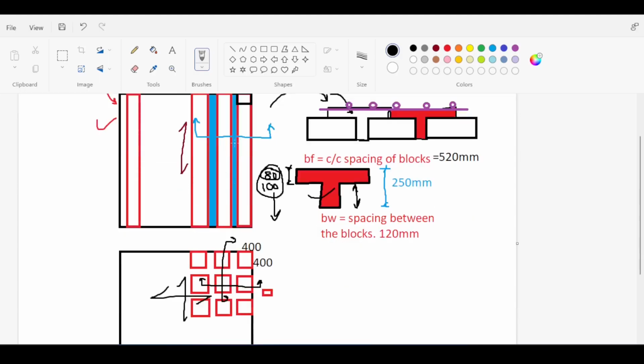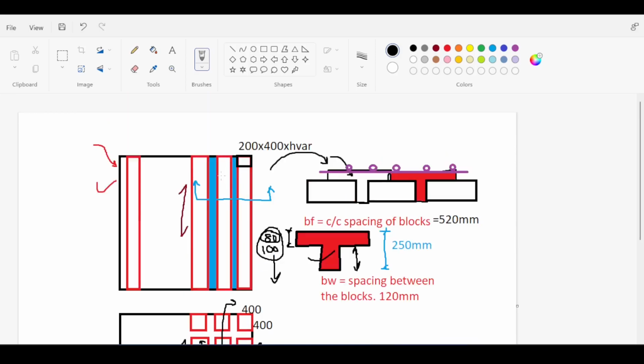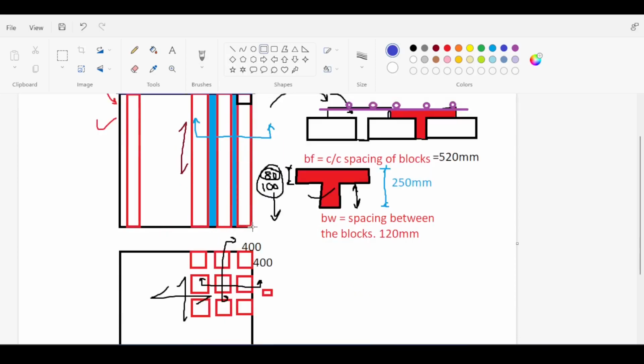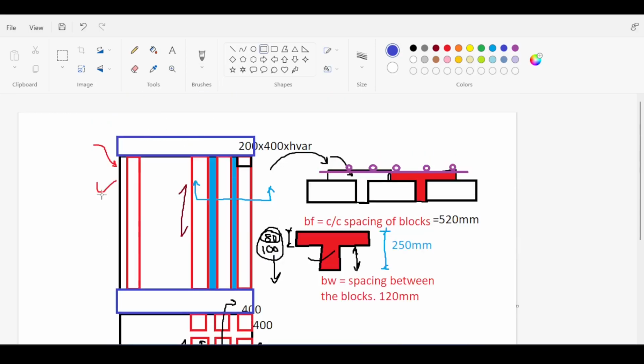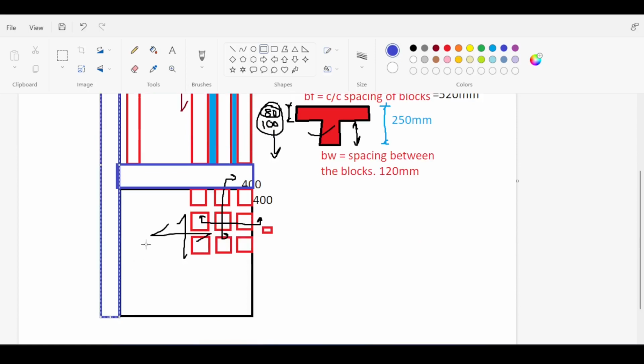Look, those ribbed slabs, those ribs, where are they going to put their load? The ribs are not connected to each column, you know, so the ribs are usually connected to a reinforced concrete beam that carries the load into a nearby column. So in the end, around the ribbed slab, you would have a reinforced concrete beam that would carry the load to the nearest column, basically, if you have those beams.